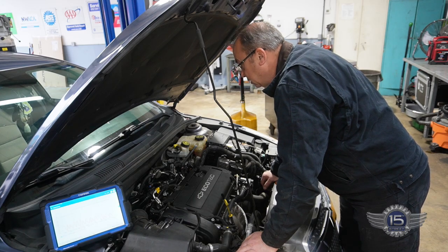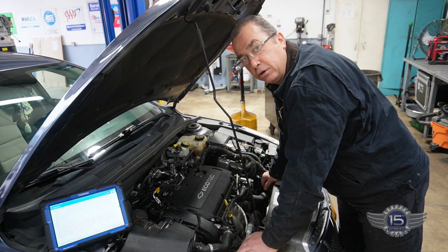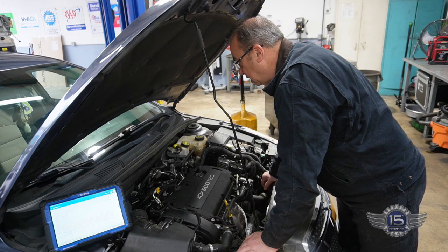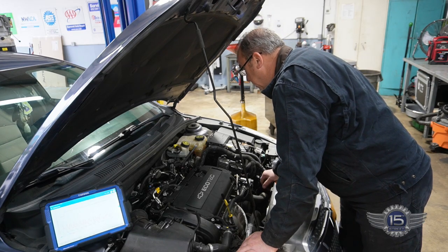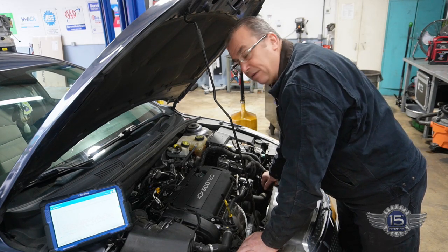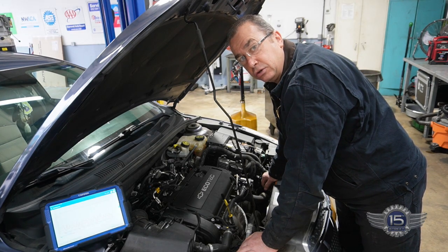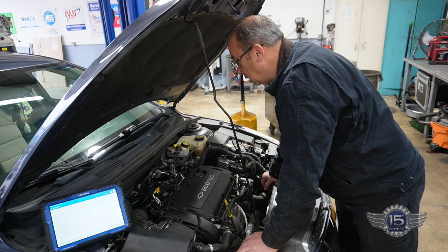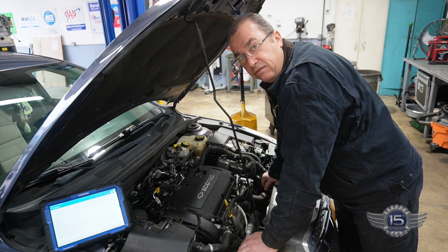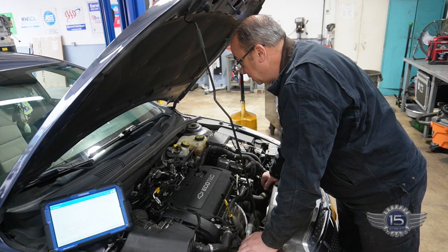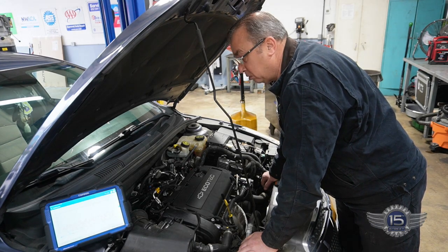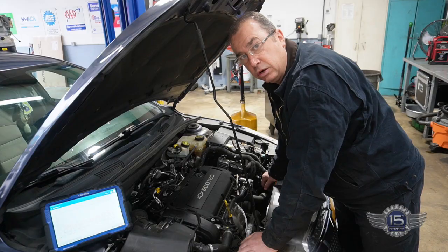I think what I need to do is smoke that purge line, and that will tell me if we're getting false air somewhere. Maybe there's a crack in the canister, but we certainly shouldn't be getting straight air out of that canister. We could have a defective vent valve too. So I'll put the smoke machine on that purge line and we'll see what's going on.